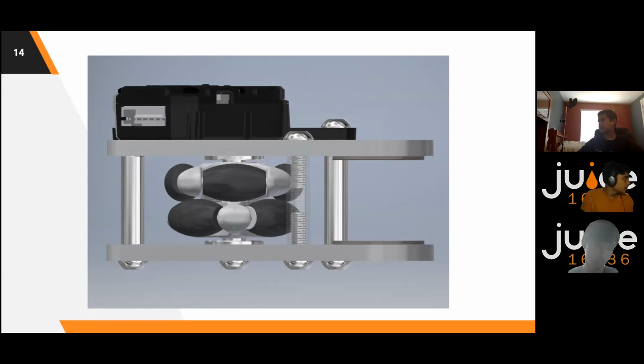Yeah, another person asked if it's possible to use odometry or PID in teleop in a way that when the driver presses a button, the robot rotates 90 degrees. This is definitely possible. We even experimented with doing that ourselves, and it would be pretty simple to do. All you would do is, I'd recommend, disable the controller input while you do the motion, then set your target for rotation to 90, and once you're close enough, re-accept the controller input and then disable your correction update, if that made sense.